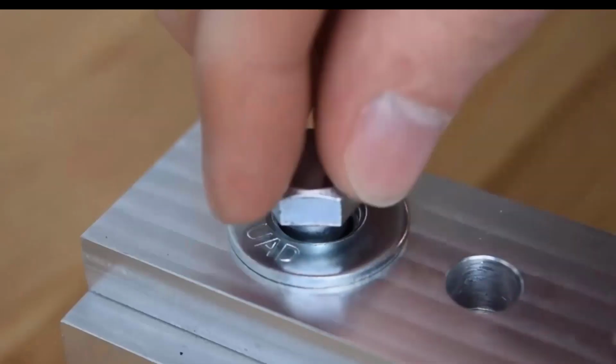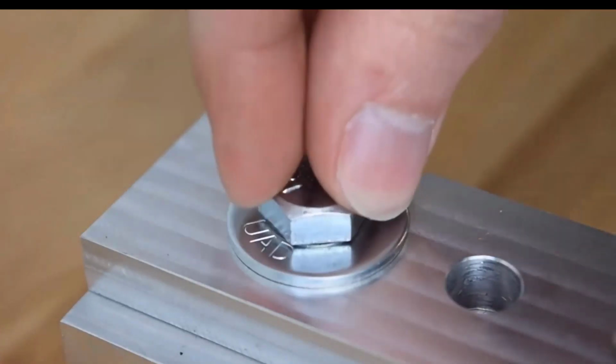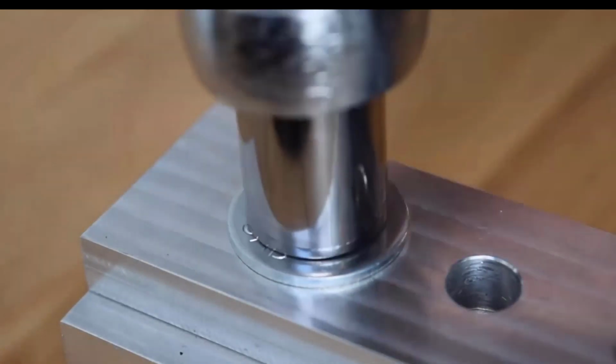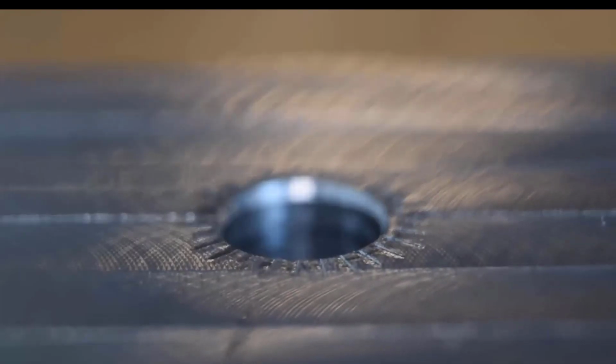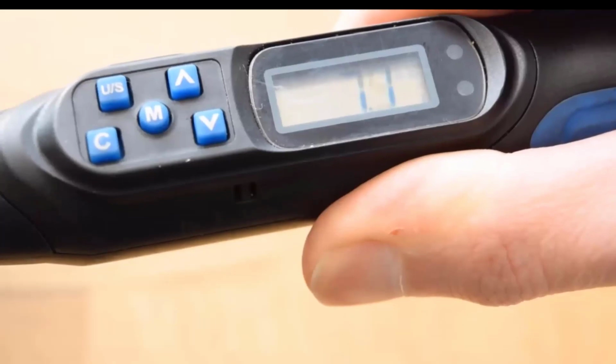Washers are used to help spread the bearing stress of bolts and nuts over a wider area. This is important if you have a loose clearance hole where only a small portion of the bolt head would be in contact with the joint members. Washers also reduce marring of the parts and make torque values more reliable.